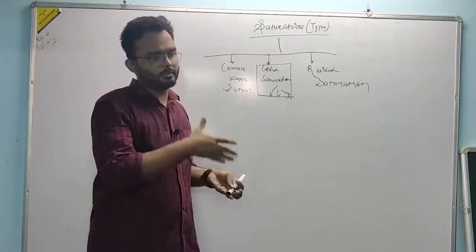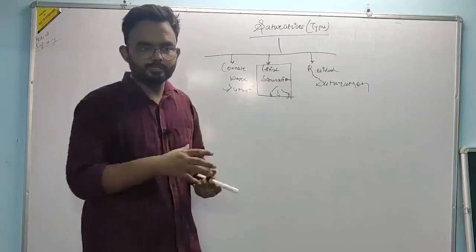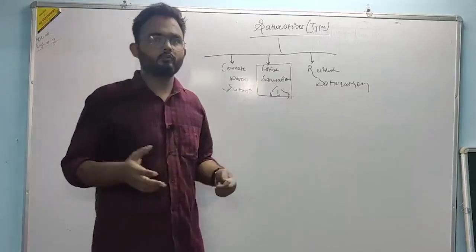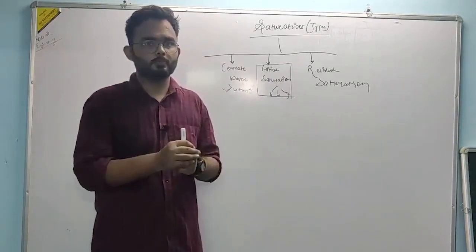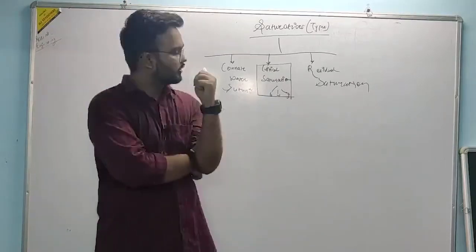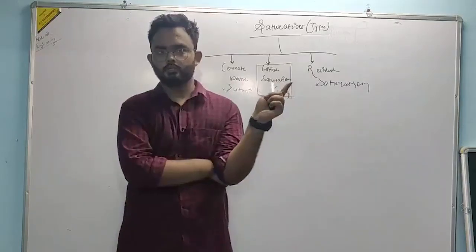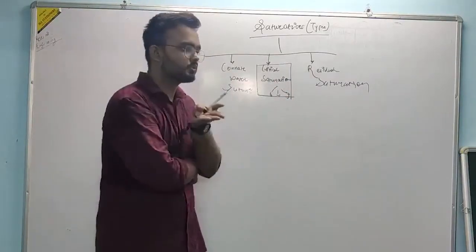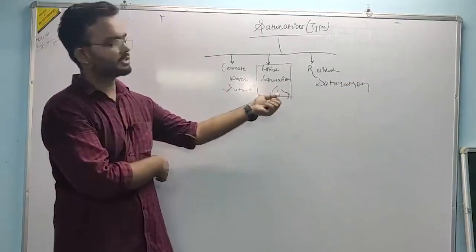Over the years, the pressure depletes and goes below bubble point. Gases try to come out of the oil. Now gases try to flow, but they cannot flow because they are disconnected and scattered. Their saturation is very low. Why gases cannot flow is because their saturation is less than something called critical saturation. They lack continuity, or a saturation good enough to develop a streamline or to develop a flow. So this is called critical saturation.